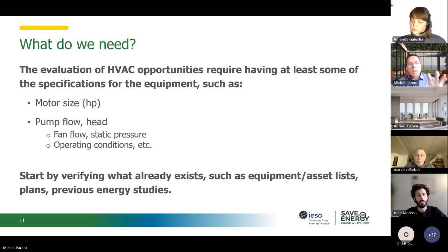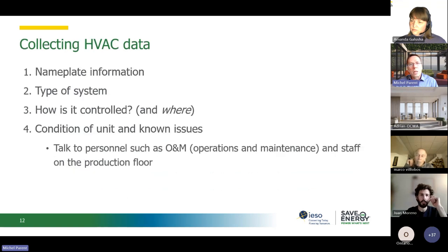So that's what you need to do, is really collect all that information, including operating conditions. Like I said, really, really important. So when you collect that HVAC data, you will obviously get the nameplate information. Like I said, very often you document that, just take a picture of it, bring it back. You know, so you have a motor efficiency, a pump has its own nameplate that you would actually collect. Like I said, how it's controlled, and you talk to the staff to know if there's issues.